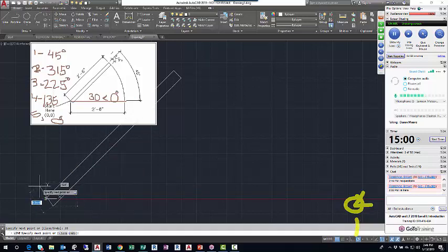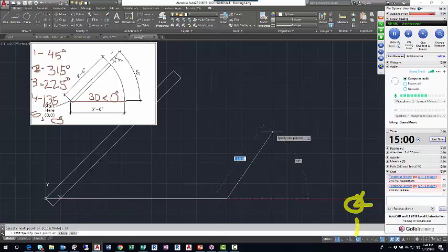All right, fourth angle. The easiest way to find this one is just point at your UCS icon or go a little beyond it, and now I can see my tracking vector. I can see my polar tooltip saying 135 degrees. I'll type in 1.75 and press enter. And finally, my last angle, this is one that I added. It's not in the book, but I think it helps. It's a 0 degree angle. I check the tooltip. I'm on my red horizontal line. There's 0 degrees. Distance is 30. And then finally, enter. Right? And then if I'm happy with what I've drawn, I'll hit escape, and that ends the command.